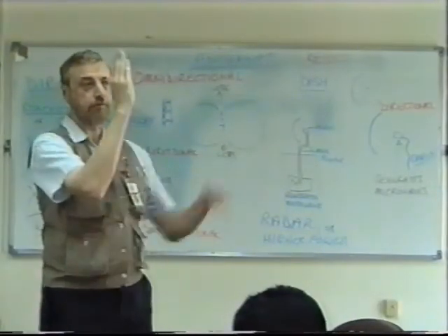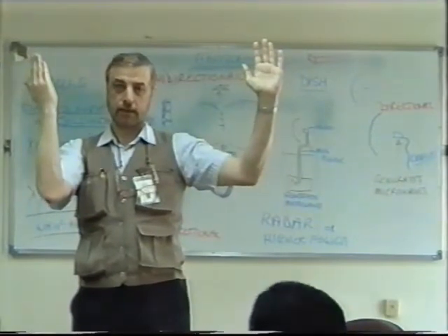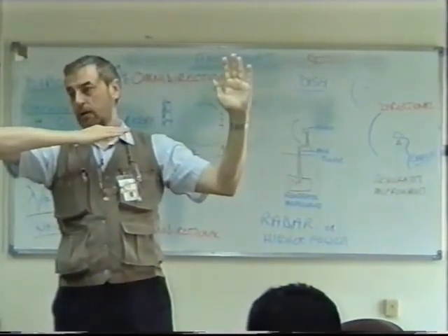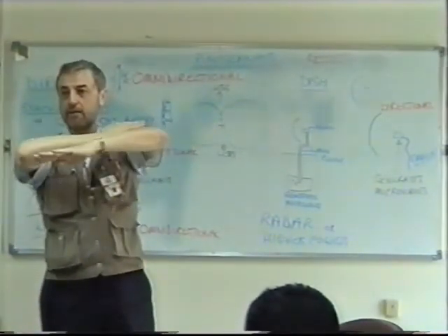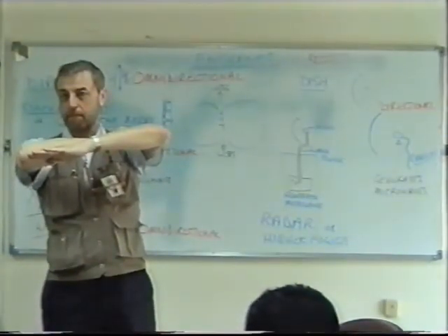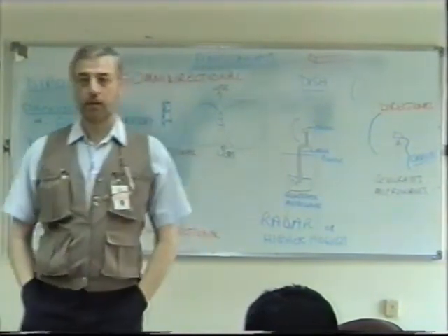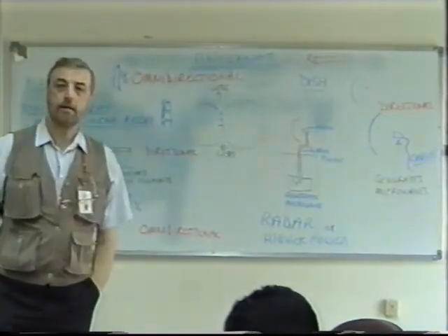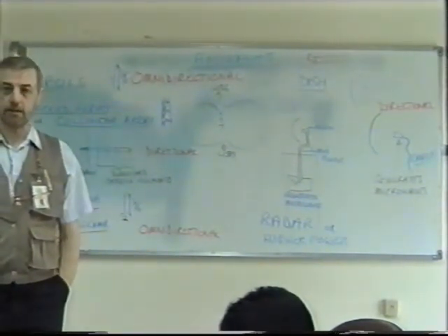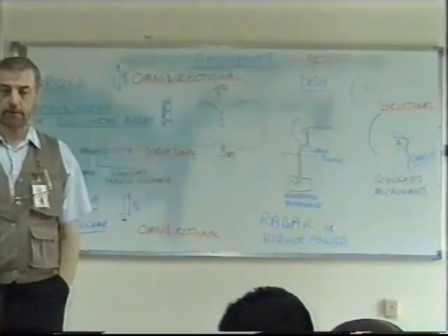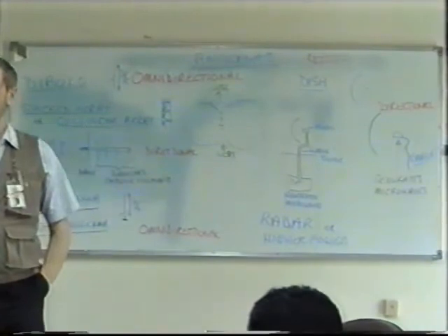A transmitted wave should be received with a vertically polarized receiving antenna, right? If your wave is horizontal, then you should put your receiver horizontal to receive it. This is particularly true for VHF, UHF. Not talking about the magnetic field, it's always the electric field direction that they're talking about, yes. When you put it horizontal, you put the antenna like this.